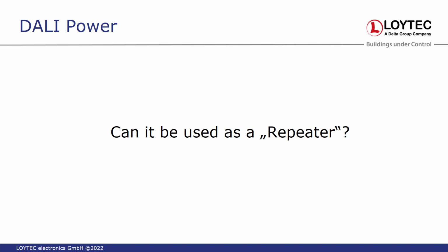No, this doesn't work. It's because this is not really a repeater. The DALI power supply is only supplying power, so it's not doing anything with the signal. The ballast and the controller is making a short on the channel, and this is what it is. I mean, the power supply only puts in the power.